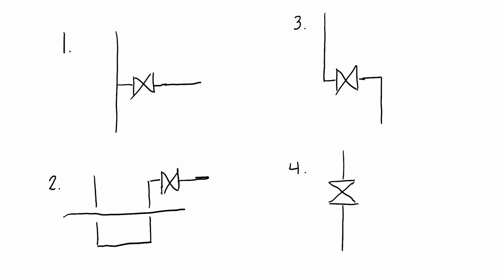So what you would want to do in those scenarios for 2 and 3, you want to do something more like number 4, which is a simplified line. Once again, this is not a pipe isometric drawing or sketch. So where this really is going to come into play is this is going to be used to follow our process in our hazard review when somebody's going out to walk it down. So it's a lot easier to look at it in this simplified format.